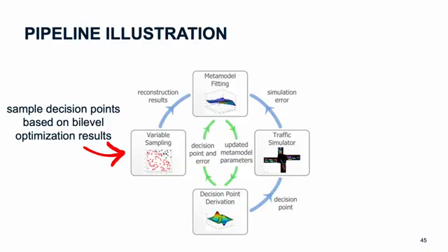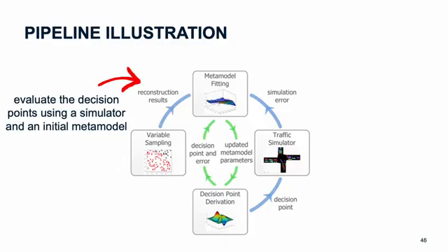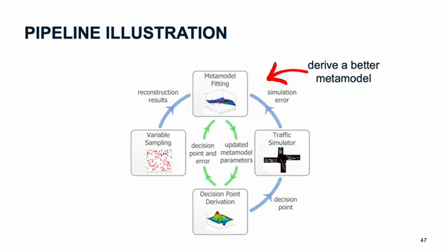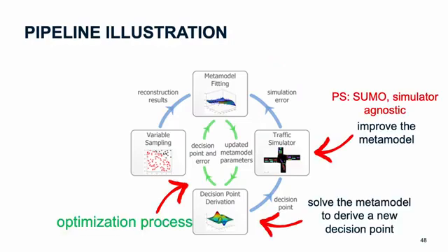Once we have done all this iterative process, we would then have a refined traffic simulation that will take into account some of the decision points regarding the turning ratio at every single intersection. We will then evaluate these decision points and incorporate them with our traffic flow simulations and traffic equations, using a full-blown simulation to fit this meta model to the traffic data, or the GPS data that we have. And we'll iterate through this whole entire process until it converges.